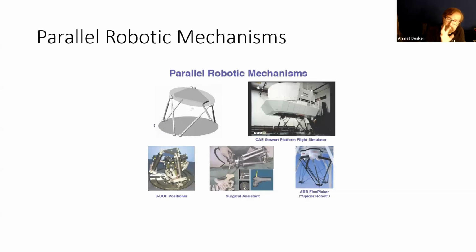Now the same trick is used here. An airplane has six basic motions. Three rotations can easily be simulated, but how can the three linear motions be simulated? We have already seen that two revolute joints can give the effect of a prismatic joint.